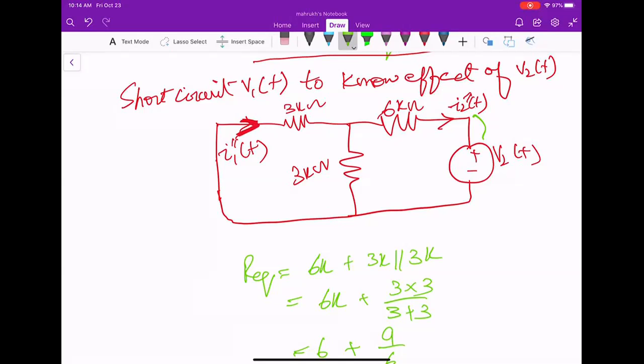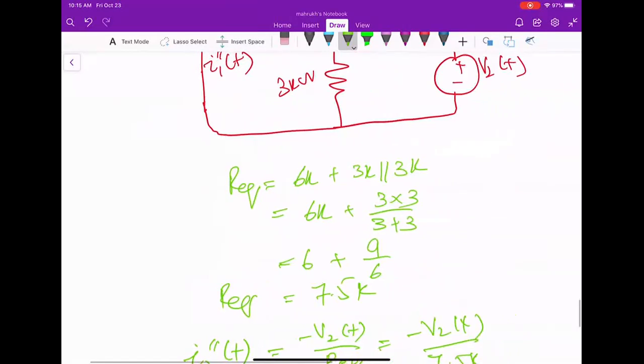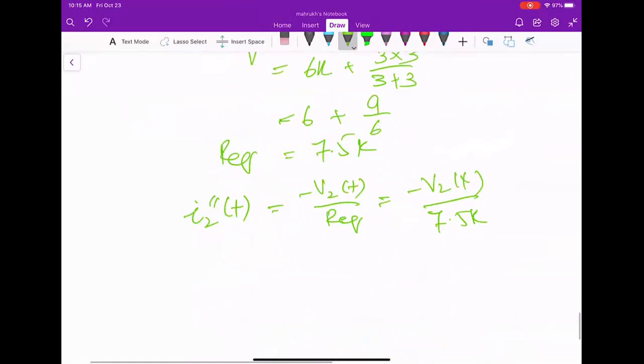It's going to be the same between both branches, so it would be like half of what we have. Oh, yes. Okay, that's another way. Or in the sophisticated way, we can say that this is a current division. So I'm just using the current division rule.